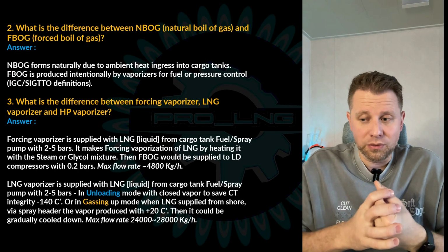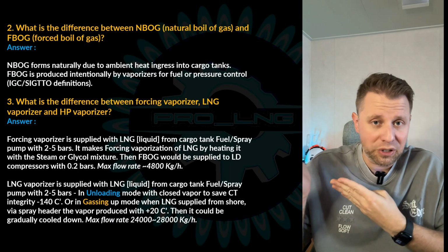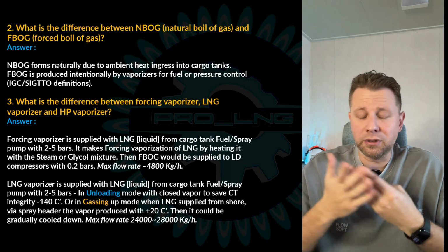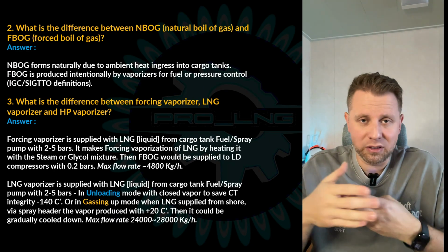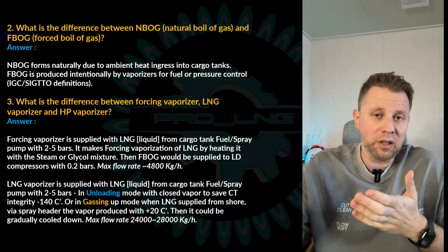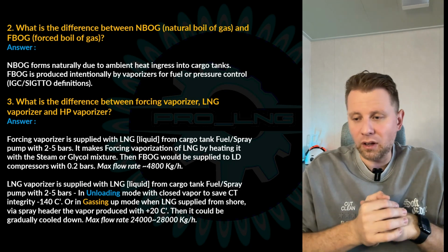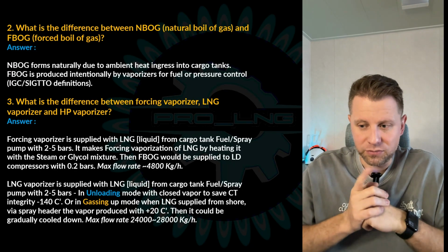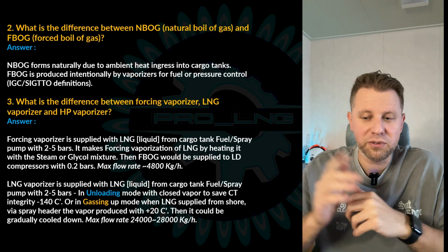Then the forced boil-off is supplied to your LD compressors, low duty or fuel gas compressors, doesn't matter, the definitions can vary, at 0.2 bars, like 200 millibars. And the flow rate here, just remember it. Look, you can see the difference already.